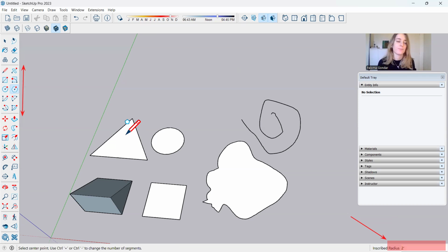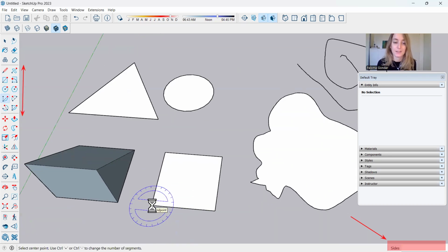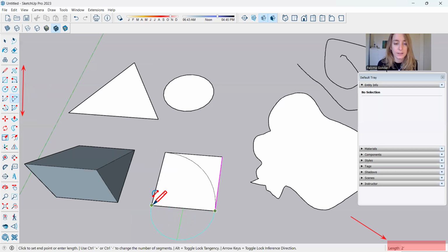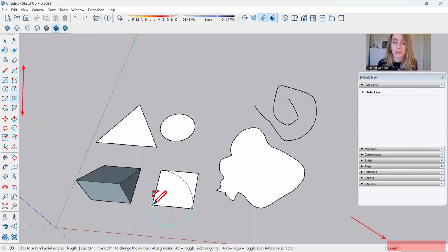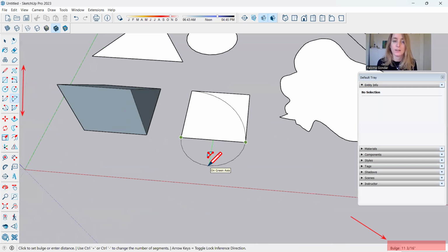Also, we have 2 point arc. So for example, I'm gonna put my center point here, my side point or end point, and then the second end point. So I create an arc, a 2-point arc. And our arc that we have is this one. So one click, second click on each corner, and then the length of this arc. So we're gonna create it like this.